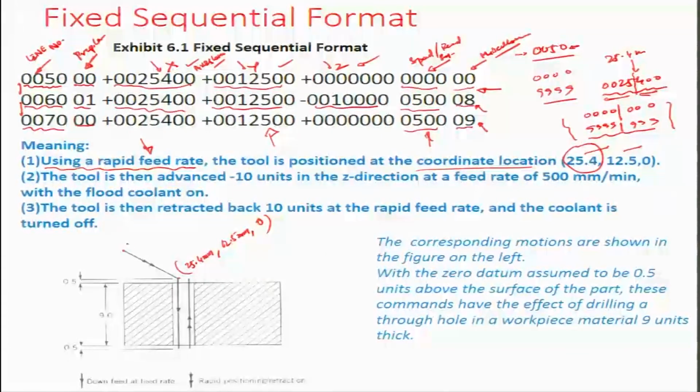So let's say the tool was positioned somewhere here corresponding to some other address, so it would read the overall XYZ motion and come to this particular position at a rapid rate. One must remember that when the tool is not engaged in the workpiece, you could use a very rapid feed strategy, but if it is engaged, then obviously the rate of material removal will define its speed of feed, and so you can't just rapidly position as you may have the luxury to do at the very beginning when the tool has still not started its interaction with the workpiece.